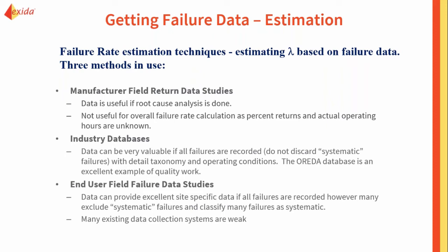If that's not going to be the same type of application you're in, those failure rates might not be the best for your calculations. If you are a valve operating inside a factory with clean conditions, you might not be experiencing the same stresses or the same issues that a valve a mile below the North Sea might see.